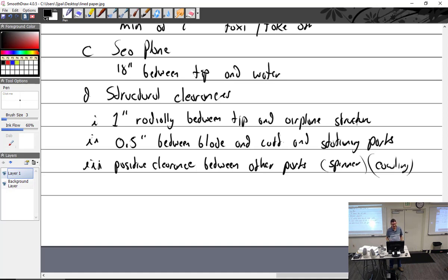That's what I want to know. Probably you're right, yeah. Engine mounts sagging or something. I'm just thinking if you ended up having soft engine mounts after some period of time. Yeah, they get soft. Flex over. Yep, they absolutely do that. Oh, what happens if you only have 1 inch and your mounts start to get soft? Oh, yeah. Once you take a chunk out of your nose,